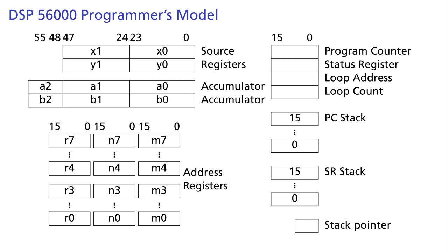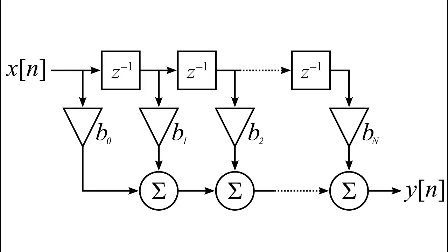To understand its design, it helps to understand a common DSP algorithm, specifically a finite impulse response, or FIR, filter. The FIR algorithm, such as it is, is a simple convolution. It transforms an infinite stream of input samples into an infinite stream of output samples. Each output sample is the sum of the product of the last, say, 100 samples with 100 fixed coefficients that were chosen by the filter designer. Thus, an FIR amounts to 100 multiply and accumulate operations on sample-coefficient pairs.